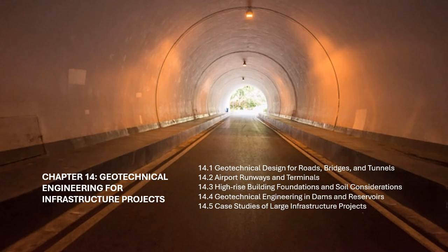Borehole drilling and sampling. Geotechnical engineers often take soil samples from different depths to determine the type of soil and its characteristics, such as moisture content, compaction, and shear strength. These samples are tested in the laboratory to evaluate factors such as consolidation behavior, plasticity, and grain size distribution.